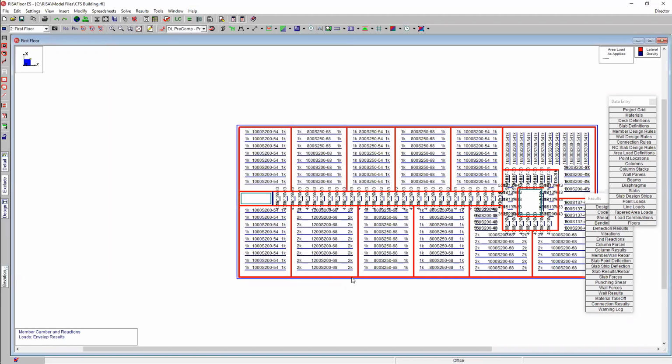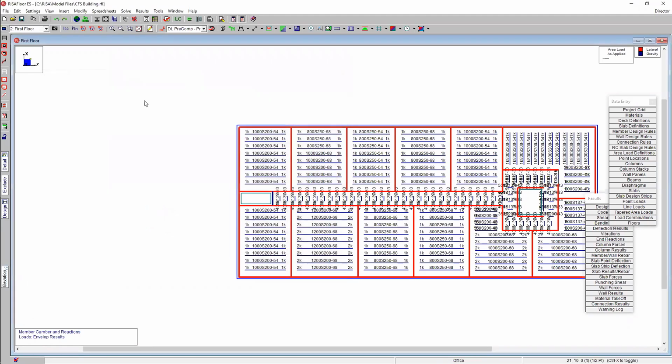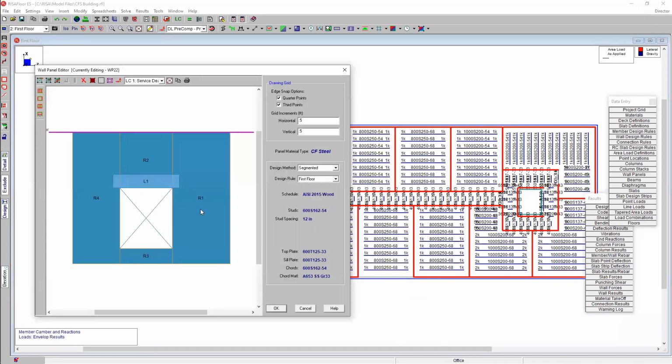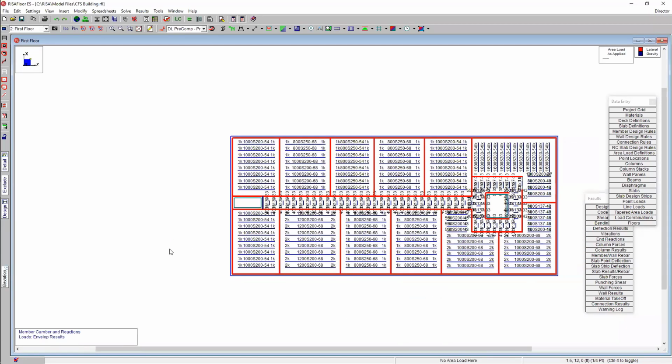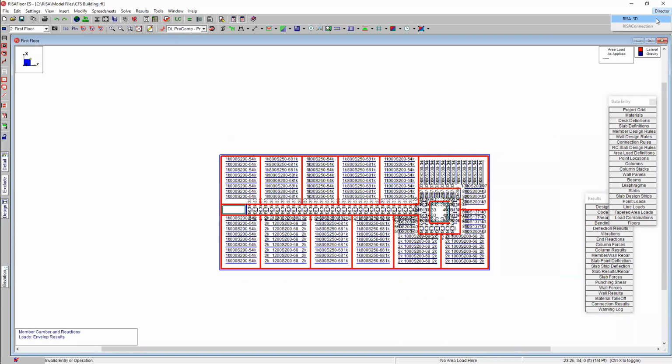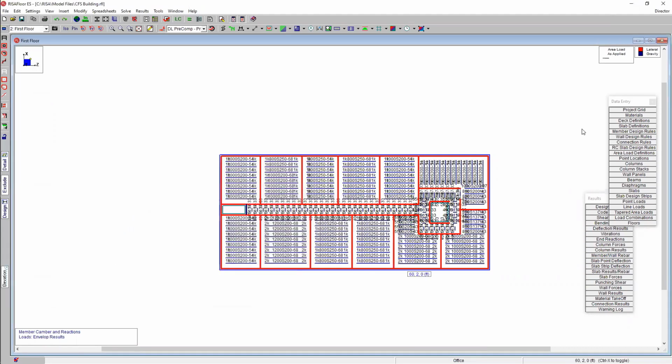And you can do a region report where you find out the summary of what's happening in there. I did put openings on these walls, kind of made them more interesting. This then with the openings starts to really talk more about that aspect ratio. So I put giant openings in this model. I think one of the things I was thinking was, this is a condo. We're trying to sell nice big bay windows. So what happens with those openings and how does that work? So let's go ahead and go into RISA 3D. Oh, and I also did put the other pieces, I put a door in there. So very similar, you just drop in a door.